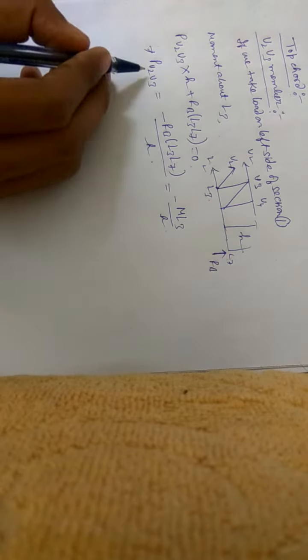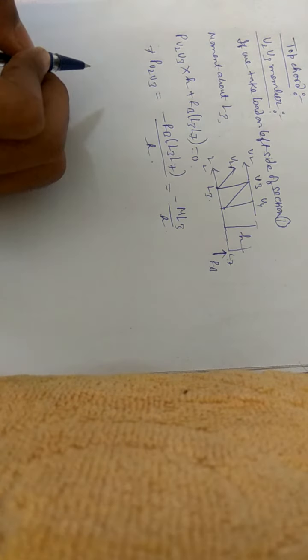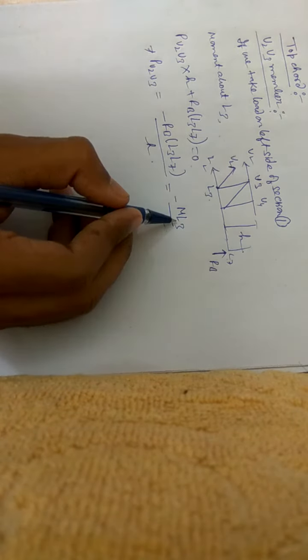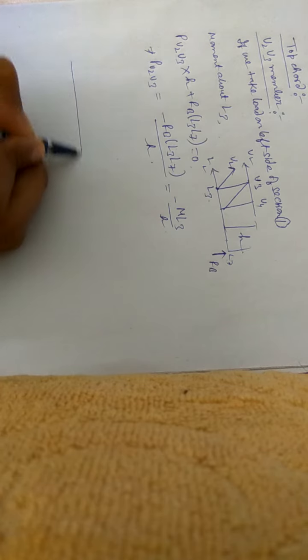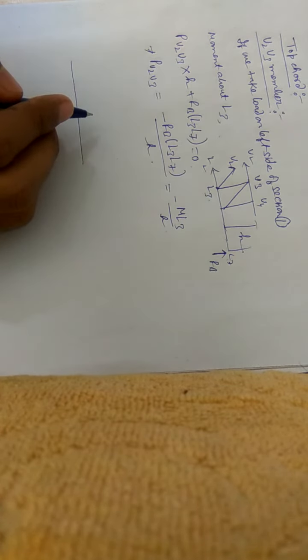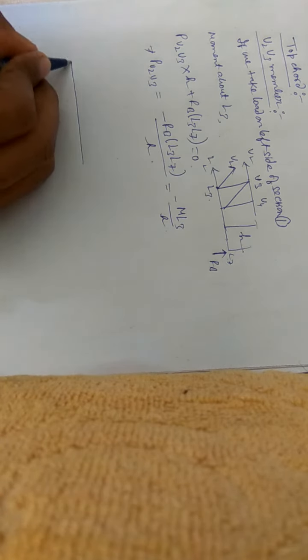So now as we have the forces, we have to draw the ILD for U2 U3. So recall what is the ILD for moment at L3.